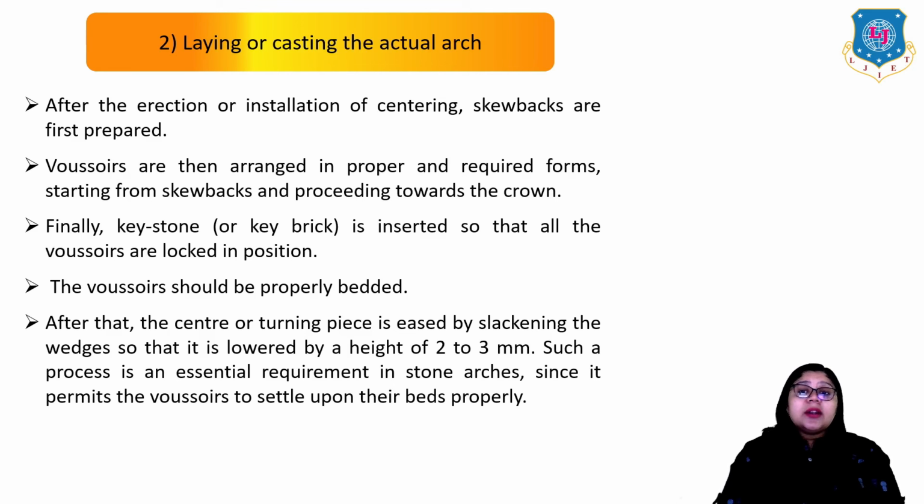After that, the center or turning piece is eased by slackening the wedges so that it is lowered by a height of 2 to 3 mm. Such a process is an essential requirement in stone arches since it permits the voussoirs to settle upon their beds properly.